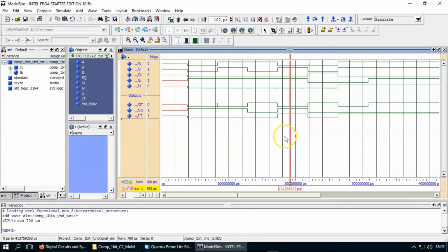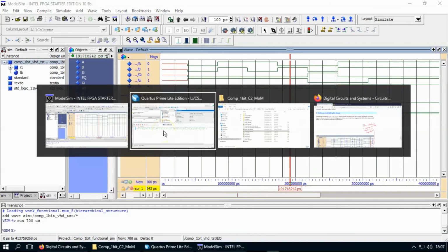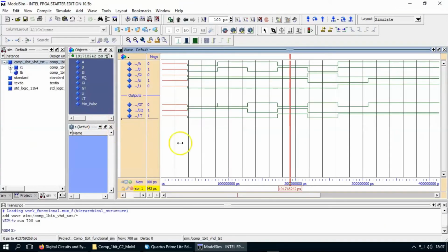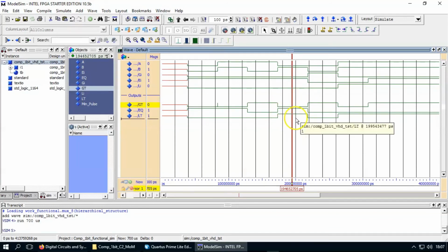So now it's time to go back and analyze again from Quartus itself what has been happening here, okay? Because the test is not ready yet, you see? So we have to go and explore again the file to see what went wrong with the transcription of the schema into the VHDL, because something is clearly wrong.